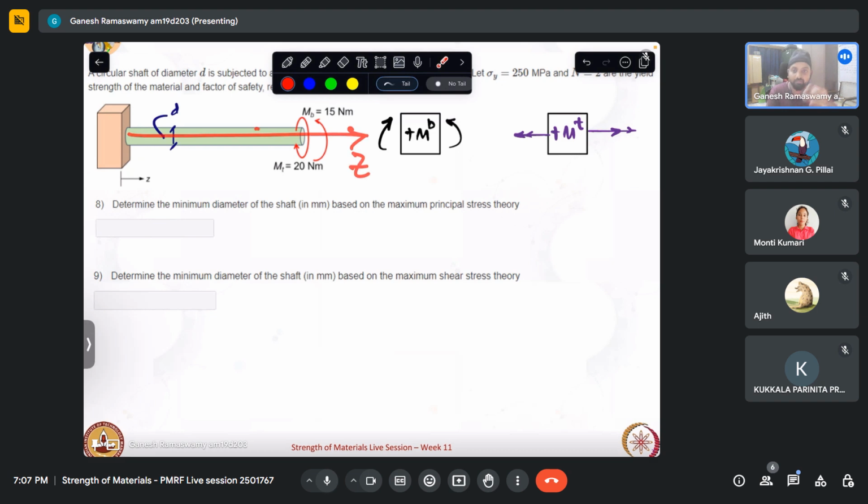So it's a matter of convenience, but we will see towards the end how to club these two together, given the fact that for beam analysis, the x direction, which is along the axis of the member, is the same as z for our twisting analysis. So based on the similarity of these two axes, we'll actually be able to simply populate the stress tensor and then see how to go about designing this shaft. So that is the sum and substance of what we are going to do. So let us go ahead and do that.